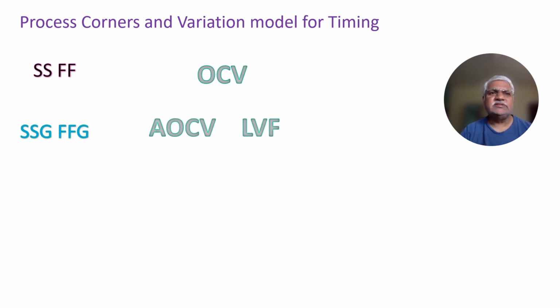And SSG, FFG and, for completeness, TTG are used along with the AOCV variation model or the Liberty variation model.